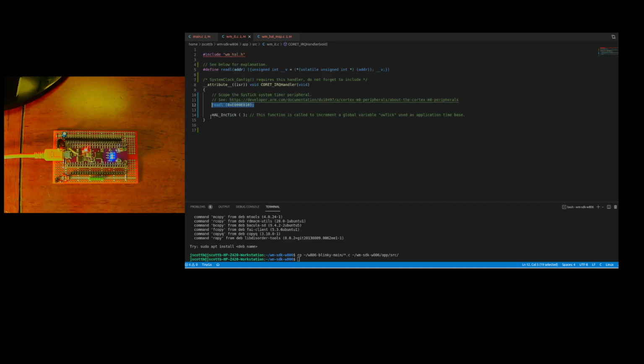And this increments the tick counter. And this is an interrupt, by the way. And you've seen this with Arduinos, I'm sure, before. So it's set up as an interrupt service handler. And so however many times this is run, this gets incremented. So it keeps your counter going for your timer.